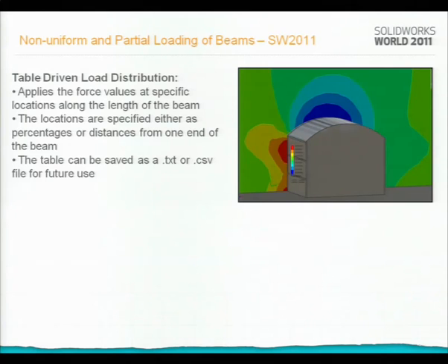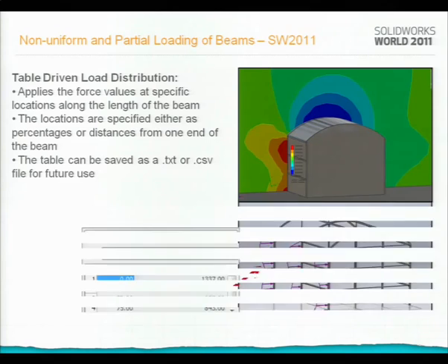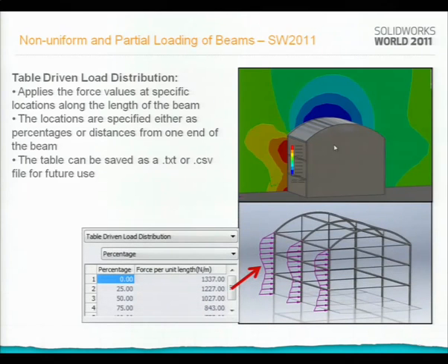So, uniform load distribution is not useful now. I cannot use triangular, parabolic, or elliptical. I have to use, in this case, table-driven load distribution. So, this is the input in SolidWorks Simulation.